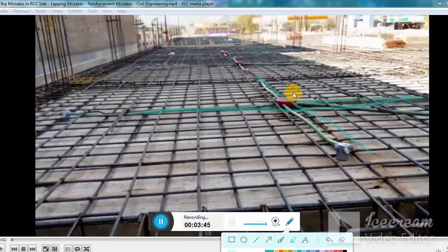Then, for example, if you see here a junction, these things matter in mega structures. Clear? The best way for such an arrangement is that you provide this kind of system on the bottom surface of the slab, and then provide sealing to hide such kind of pipes. Okay, so that is a good practice. We should never allow such a conduit system, because it creates a weaker section in some places.